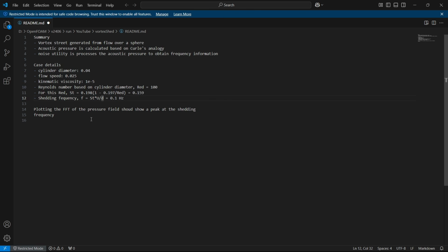If you want to know what the Strouhal number is, I have made a video on how to calculate the Strouhal number using ANSYS. I will give the link in the description. You can check it out. And based on that, if we do the fast Fourier transform, which is the FFT, you will be able to get the shedding frequency. Okay, so you take the Strouhal number and it will be like a wave-like thing. Okay, so you take the waves, and if you do the fast Fourier transform, you will get the peak at which the shedding is happening, which will give you the frequency. And in this case they have calculated it.